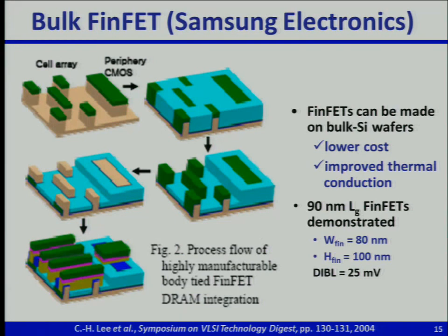So the way to do it is you still draw a wider active area, the transistor area, but you have multiple fins. Now, circuit designers need to be able to accurately predict transistor performance. The modeling of how the FinFET current increases with the number of fins is kind of tricky, because if you have multiple fins in parallel, the outer fins are narrower than the inner fins, so it's not trivial. And then also, if you want to increase the current flowing in a FinFET, you have to increase it by increasing the number of fins. That means it's quantized. You have to increase it in steps, and so that's not trivial.